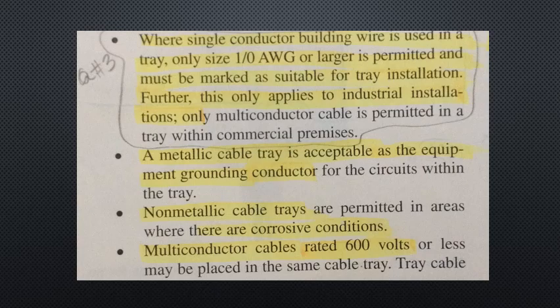Cable trays. Cable trays are open cable supporting assemblies used in a variety of commercial and industrial buildings. Cable trays are not enclosed, so they do not fit the description of raceways, but they have the same function. Tray systems are fully recognized as an approved method of wiring.